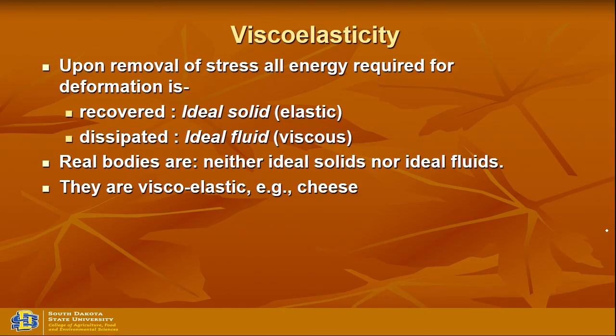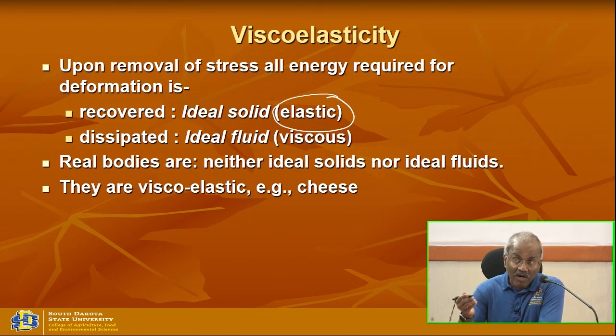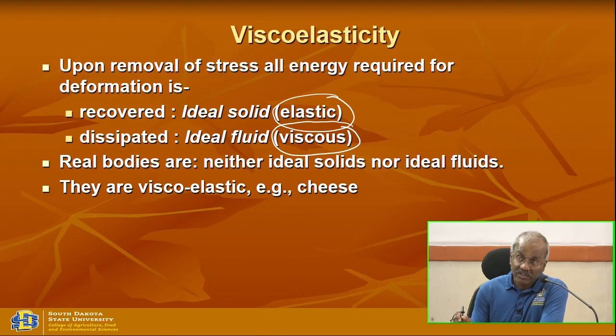Because an ideal solid is elastic, and primarily it is a spring model. So whatever you deform, it will come back to the original position. All the energy is recovered. But in the viscous model, the ideal fluid, all the energy is dissipated. Nothing is coming back. But real bodies are neither ideal solids nor ideal fluids. They are a combination of viscous nature and elastic nature.